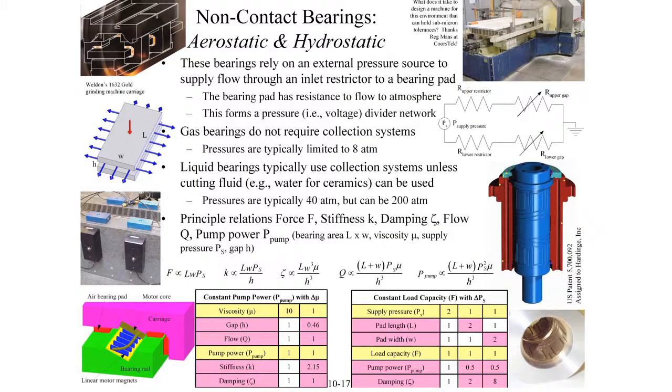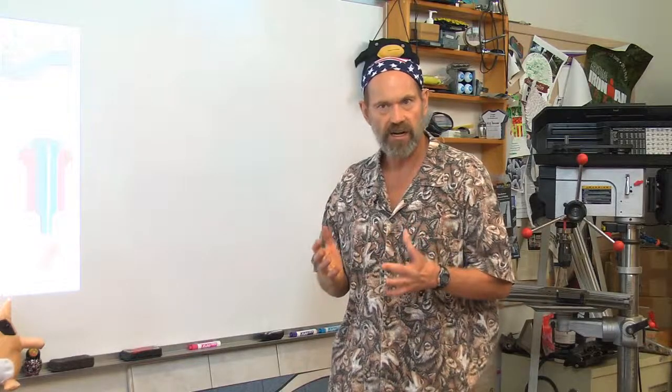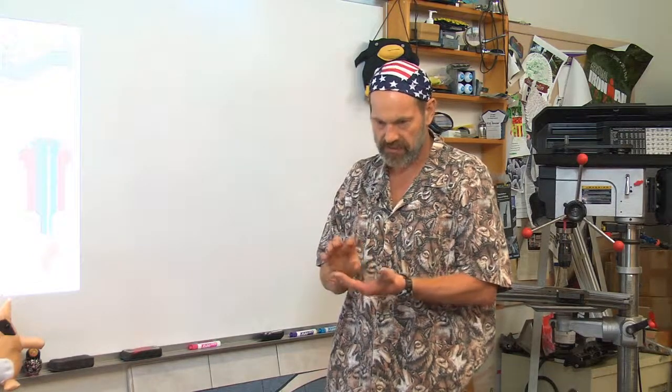Well, we just said that hydrodynamic bearings work very well because when you have a small deflection in the shaft, that's what enables the hydrodynamic wedge to build up in the first place so it can support a load. But what if I need a high degree of accuracy where I must always know the position of the shaft in a spindle, and have it be as stiff as possible?